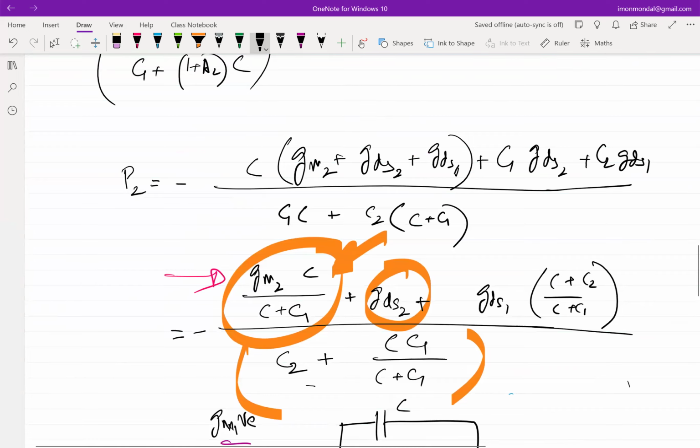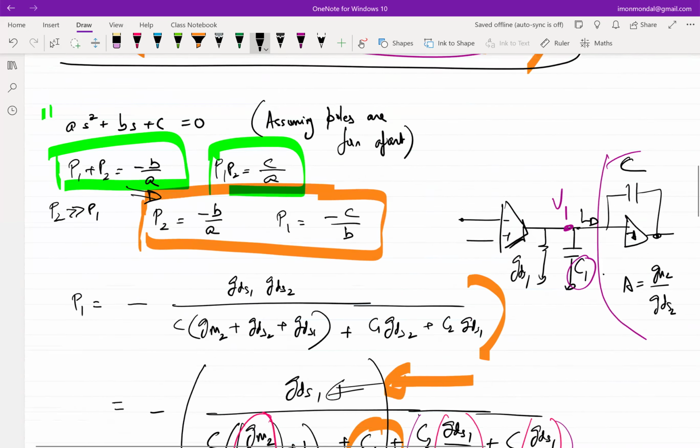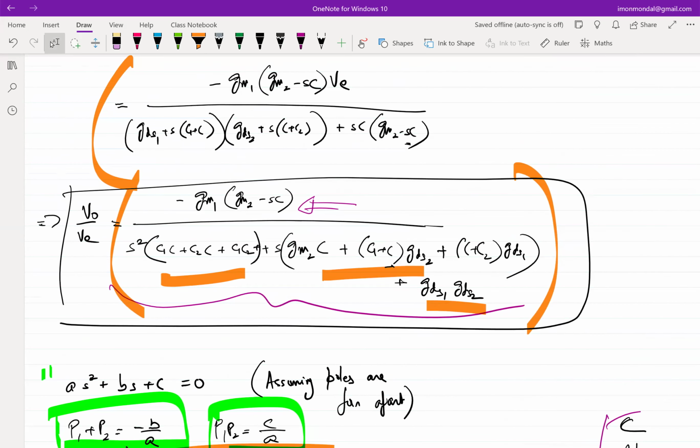The other characteristics that I will not get into, for those of you who have been following, you will see that there is an explicit zero also, right? But it's a right-hand side zero. The right-hand side zero gives you a phase lag, right? A left-hand side zero gives you a phase lead. A right-hand side zero gives you a phase lag. Now, if you have a phase lag, your magnitude response will go up, but you are getting phase lag. It's a double whammy in a certain way, right? Your phase margin is going to get affected because of this extra phase lag.